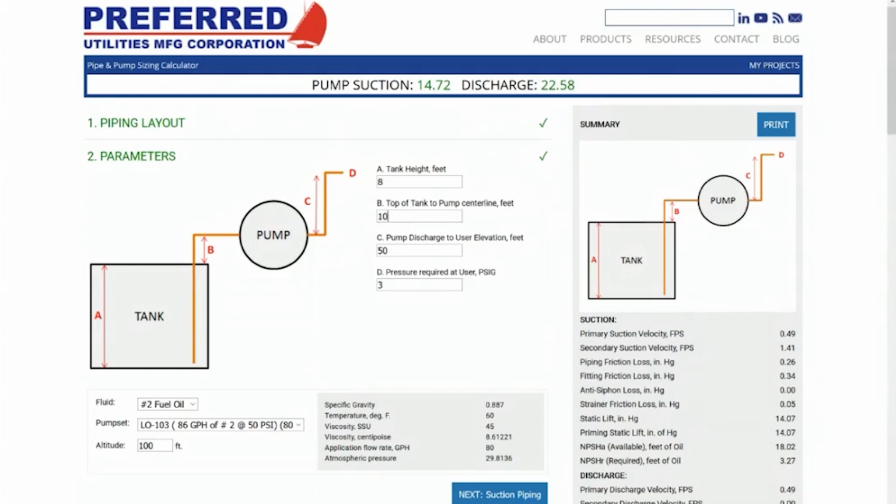We can do up to 18, 20 in some cases in the field, but there are things that change between the design phase and in the field, and typically it's not going to make it easier on the system. So I like to leave a little bit of cushion. Once we get up above 20 inches of mercury, that's where we're likely to see cavitation, and we're going to see a degradation of pump performance and lifespan as well.